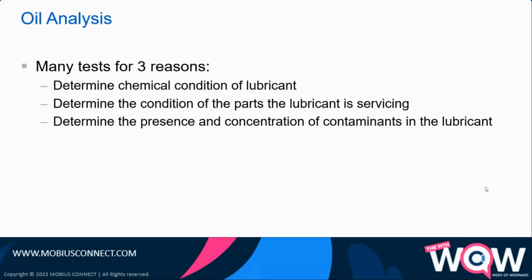Wear particle analysis is a key and standard test with oil analysis, and it can determine ferrous and non-ferrous metal particles that exist in your oil. That tells you if there is some mechanical component that is breaking down as well. And the other nice thing about it is through a microscope, you can look at the shape of the actual particles, and it can help you understand what the potential failure modes are as well.